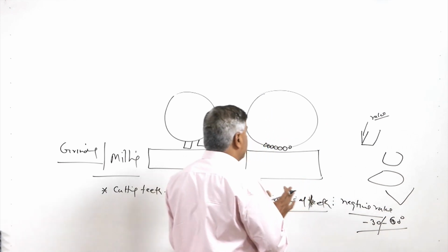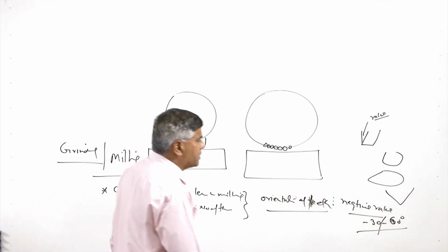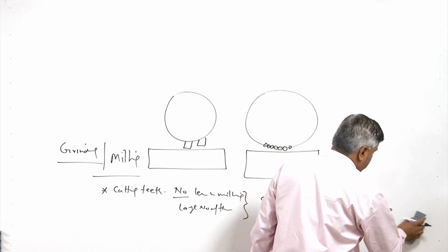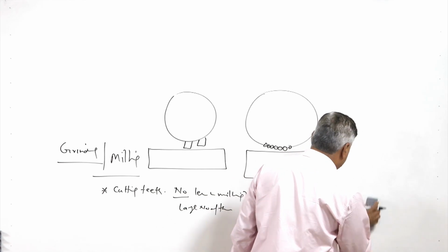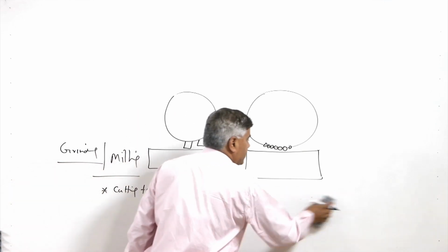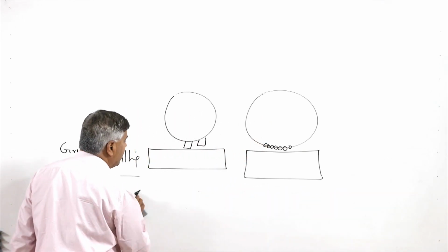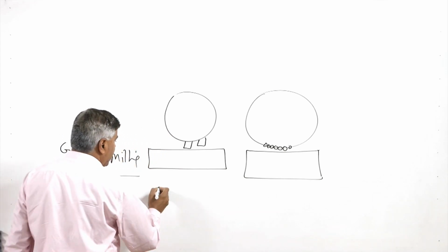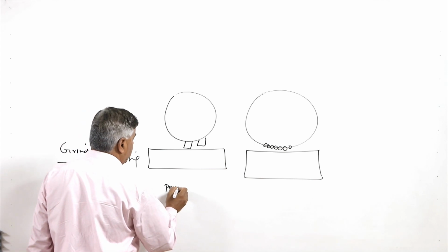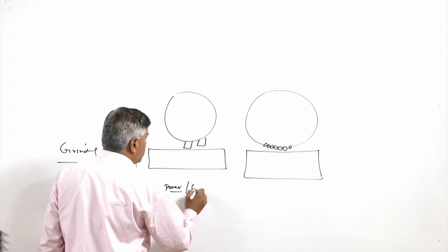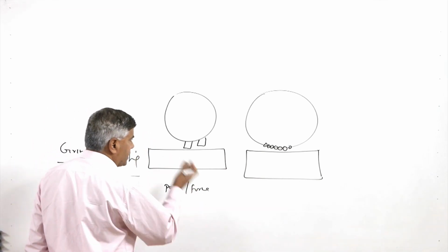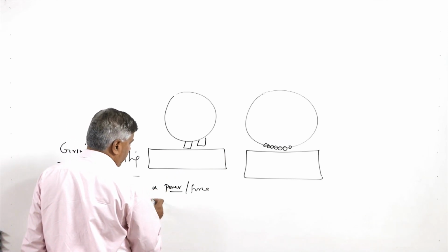We know that when a positive rake is used, it results in a higher shear angle and lowers the cutting forces acting on the tool during machining, as compared to when grinding is performed. So, the negative rake leads to a higher power requirement and more forces acting on the abrasives as compared to those on the tooth in milling.